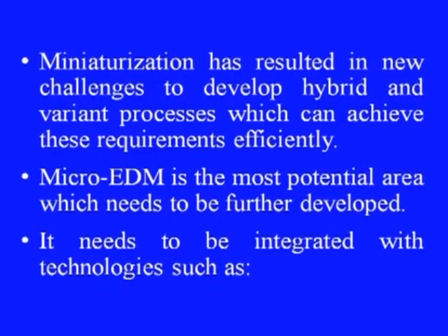Miniaturization has resulted in new challenges to develop hybrid and variant processes which can achieve these requirements efficiently. Micro EDM is the most potential area which needs to be further developed. It needs to be integrated with technologies such as magnetic assisted EDM, abrasive assisted EDM and ultrasonically assisted EDM for conducting materials. ECDM and powder EDM for machining of non-conducting materials, ceramics and composites are better options.